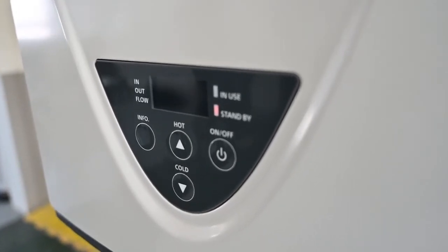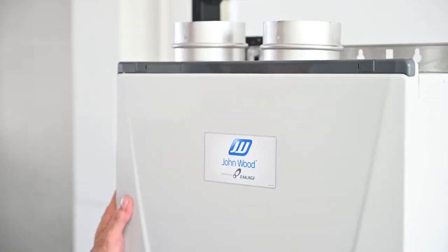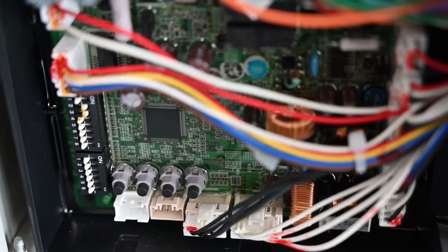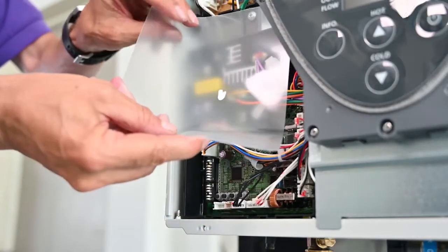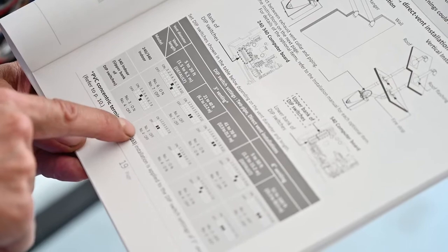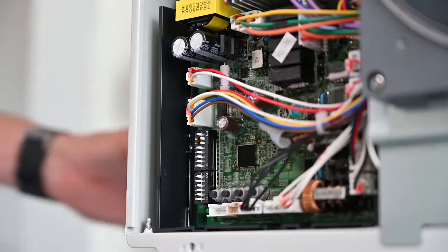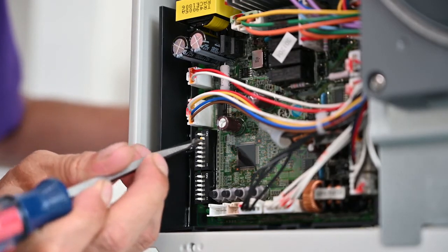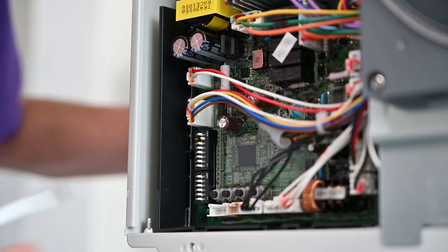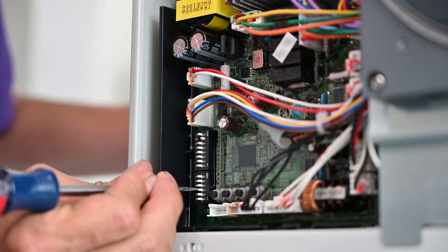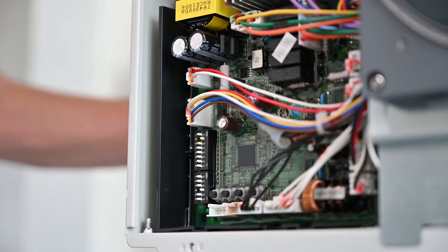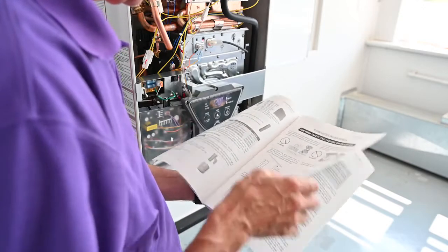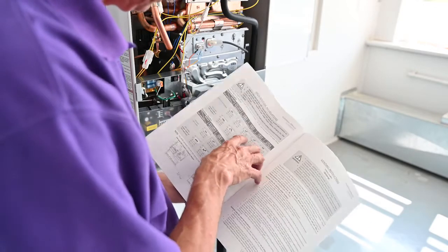and municipal codes. Something that is often overlooked during the installation of a tankless water heater is the configuration of the various dip switches. The individual switches need to be adjusted depending on how and where the water heater is installed. For example, there are switches that need to be set in a specific order based on your altitude, the vent diameter, the vent length, and whether your installation has a single or double pipe configuration. The dip switch settings are unique for every tankless water heater model, so it is very important to refer to